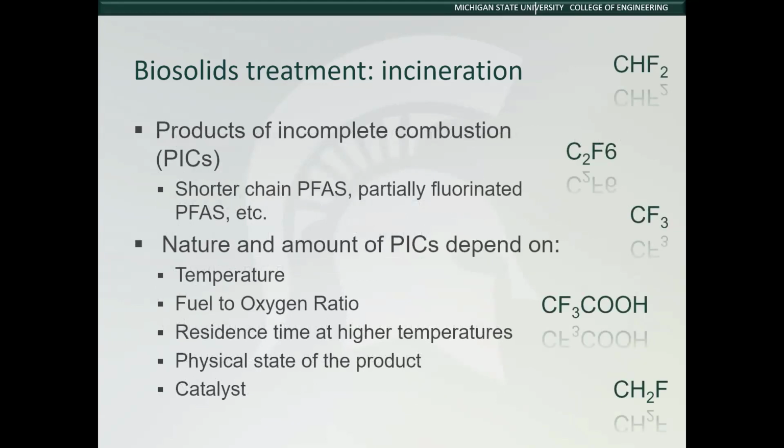As I mentioned, one of the biggest challenges of incineration is the need to monitor and characterize the emissions for products of incomplete combustion. And these include the shorter chain PFAS, partially fluorinated PFAS, etc. The nature and amount of these products of incomplete combustion depend on such factors as temperature, fuel to oxygen ratio, residence time in the incinerator, physical state of the product, and the catalyst that is used.